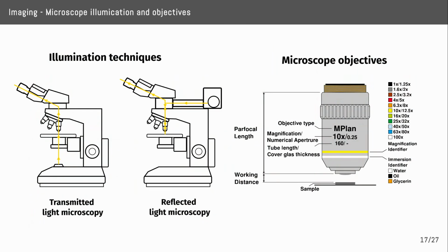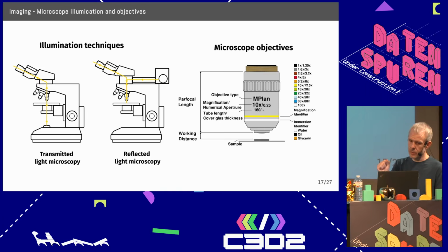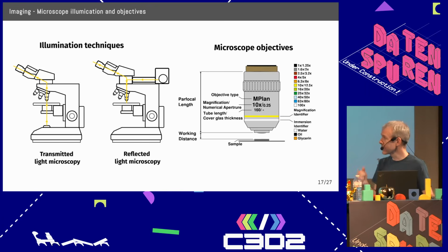So now we want to image. We have a delayered chip, or we have the decapped chip. And at first you have to get a microscope. The standard microscope that you might all know is the transmitted light microscopy technique. It's the biological microscopes. So you have light which comes from beneath. It shines through the sample into the objective, and then it comes out of the eyepiece. This is a problem because visible light cannot transmit through the chip itself.